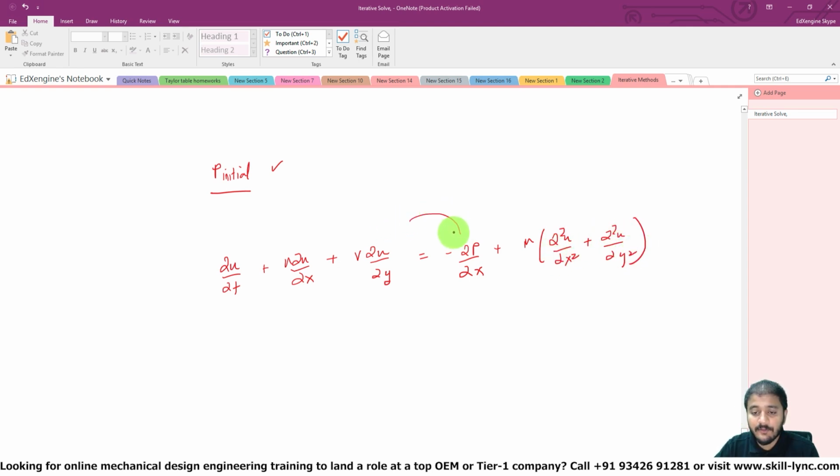Now once we put our initial conditions here, with this you can calculate a value for velocity, correct? Now this value of velocity is not going to make sense if you take it and put it in ∂u/∂x plus ∂v/∂y, it's not going to be equal to 0, right? So what we have to do is derive an equation which helps us get a pressure value which will satisfy the continuity equation.